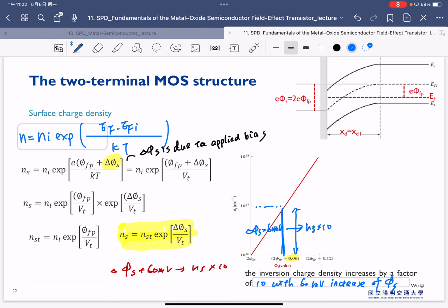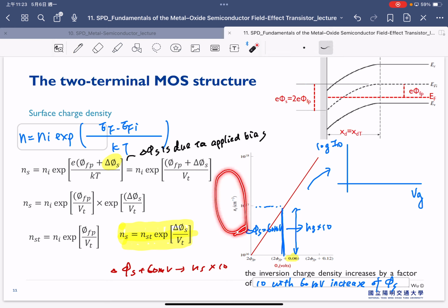And this becomes very important because this becomes the bottleneck for our advanced semiconductor transistor. If you try to read further interpretation for these things, this is actually correlated with our current, which we can also plot as the log drain current versus our gate bias here, because we know the charge density is related to our current.